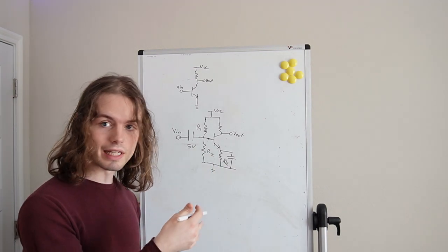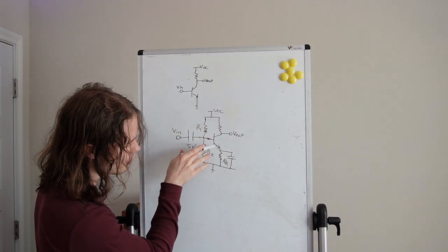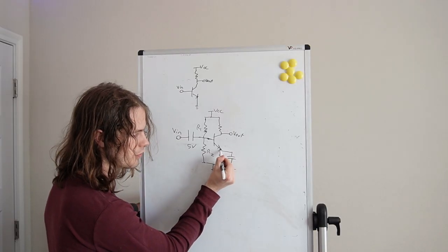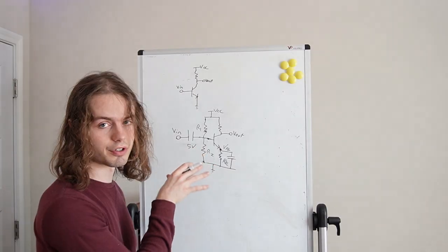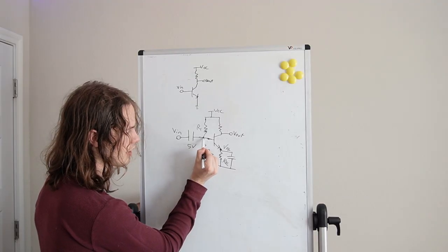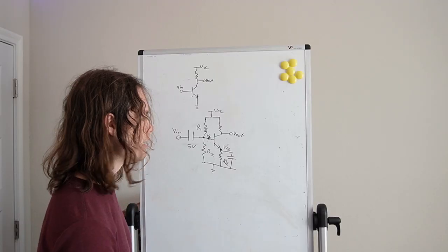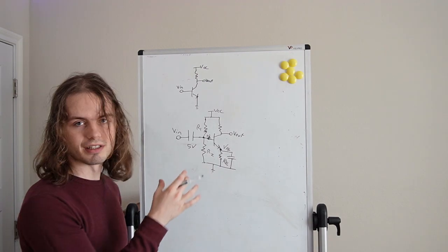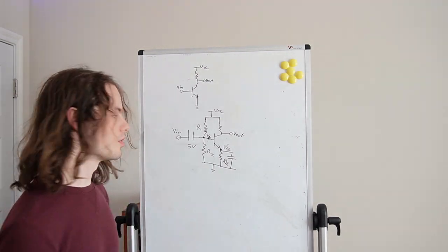it employs negative feedback. As you can visualize here, if you have current going through this transistor, it's going to go through this resistor, which means that the voltage here, VE, will increase as you have more collector current. But if VE increases, and we know that this point here, VB, is being set by a resistor divider, that means if this VE goes too high, this junction will stop conducting. In reality, it finds an analog stability point. So that's how it works.